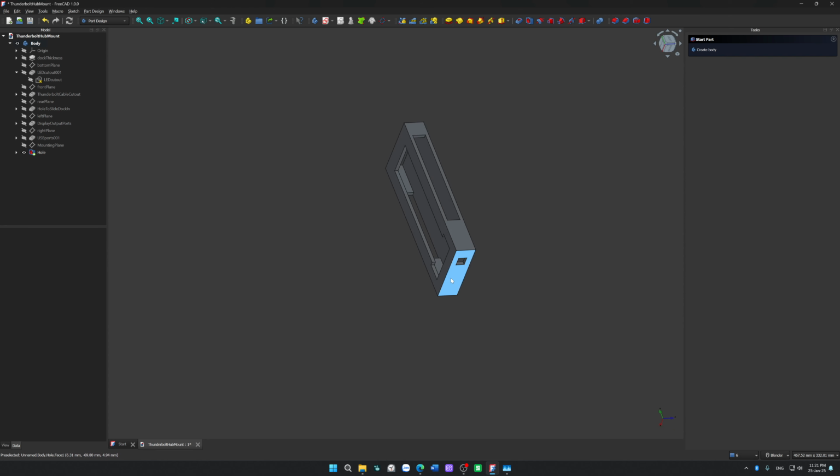So this will be the face that touches the bottom. The rest will be just walls. They will print it like this, so the layer lines are not a weakness, because it will be printed the easy way, the flat way.